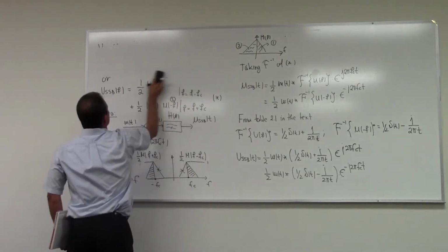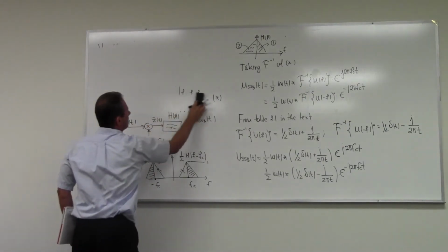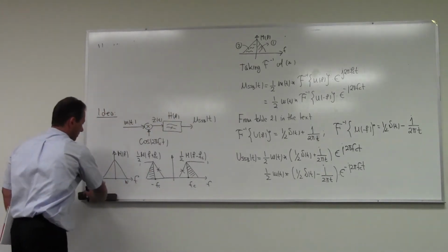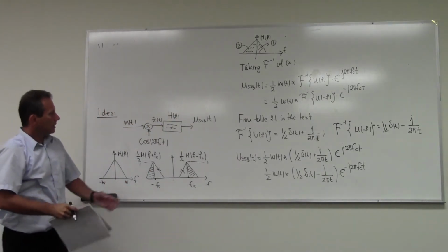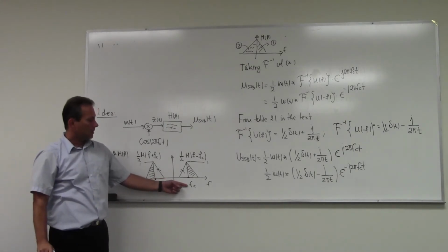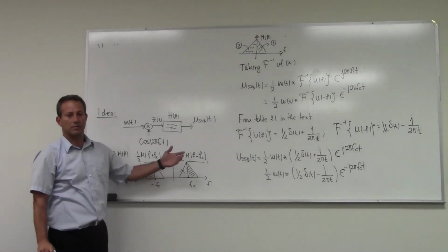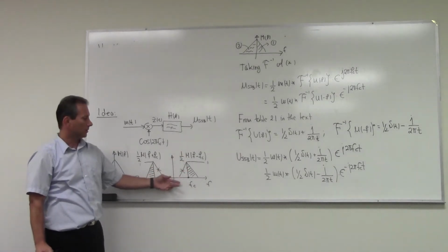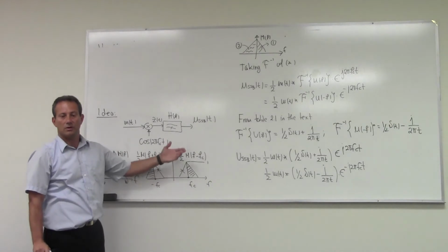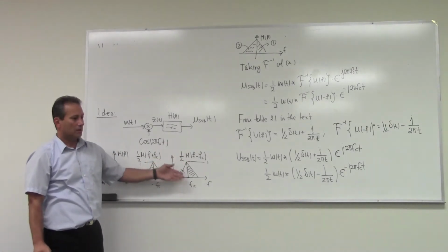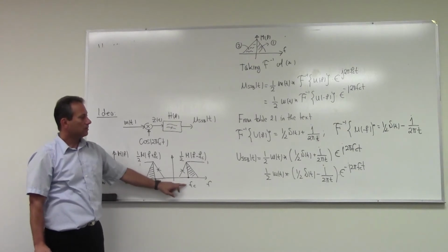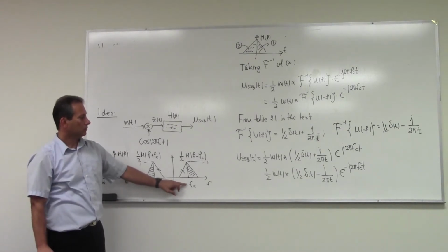I haven't really mentioned it, but let me explain why we need to do processing in a baseband. Look at this, fc can be relatively high in frequency. For example, if you're doing radio broadcast, then you're translating to hundreds of megahertz. If you're doing cellular broadcast, it can be several hundreds of megahertz, even a few gigahertz, right? So fc can be very high relative to W, right?